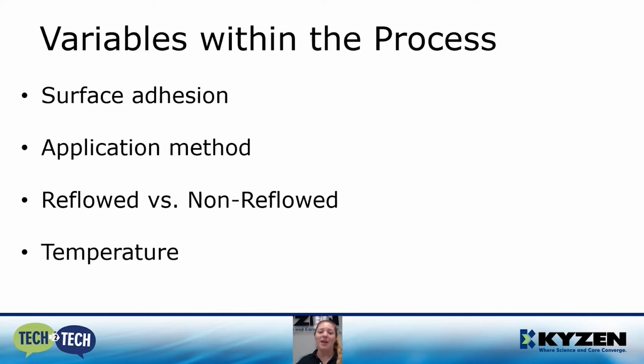If there's contamination already on the board and you're trying to put a label over it, that can cause improper adhesion. And then just a poor match between the adhesive and the substrate that you're putting it on. It's like trying to stick saran wrap to plastic sometimes. It doesn't always work. So having that good combination always helps.